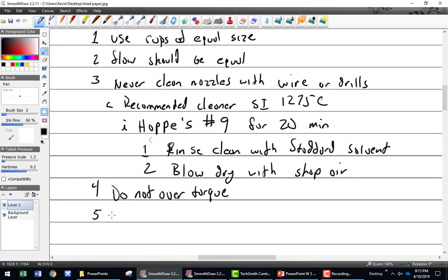Okay. So most people are pretty good about that. But then they go to put the injector lines on top, and that's where they really go crazy with the torque. And nobody wants to torque it. It's easy to torque the nozzles in because, 7/16 or half inch? It goes right over a deep socket, just fine. Torque it, no problem. Now you got to put the lines on, and it's got a line in the middle. Well, how are you going to get a wrench on that? Well, now you got to get a crow's foot. Nobody wants to do that, and so, just a little tight.